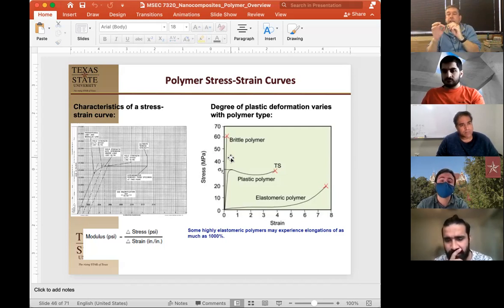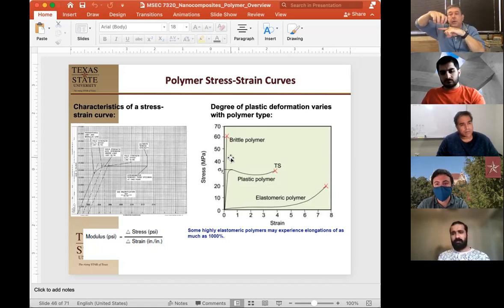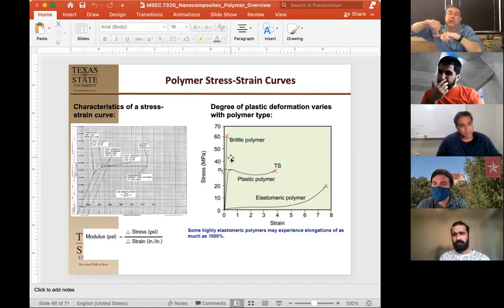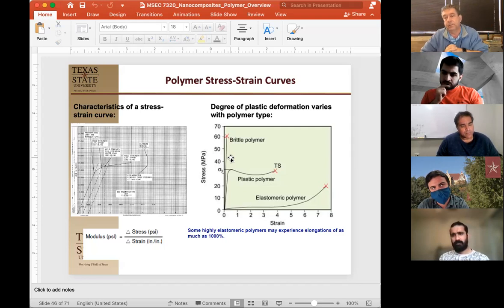So it's not just if you had a thin one, how much it would deform, it's how much that is deforming with all of its elastic material behind it. So all durometer readings are talking about how much a probe can penetrate into a rubber material at a specific force. And so you have multiple durometers, like a durometer 50 is a little bit firm, but a durometer 75 would be firmer. And so the penetrometer would go in less distance. Does that make sense? Okay.